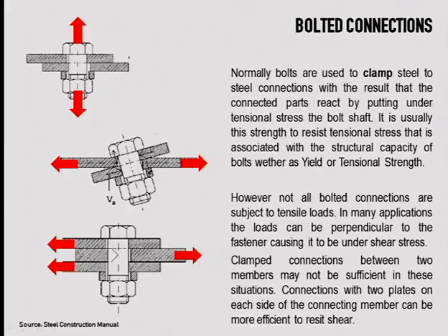But when we have horizontal forces, so that there is shear involved, that is not the ideal situation for the bolt. So what happens? In that case, a common solution is that you insert a 3rd plate so that you clamp first the plates and then you place the bolt. So to try to reduce, to contrast shear forces. Okay, shear is always this type of movement. It's the mutual friction of elements.